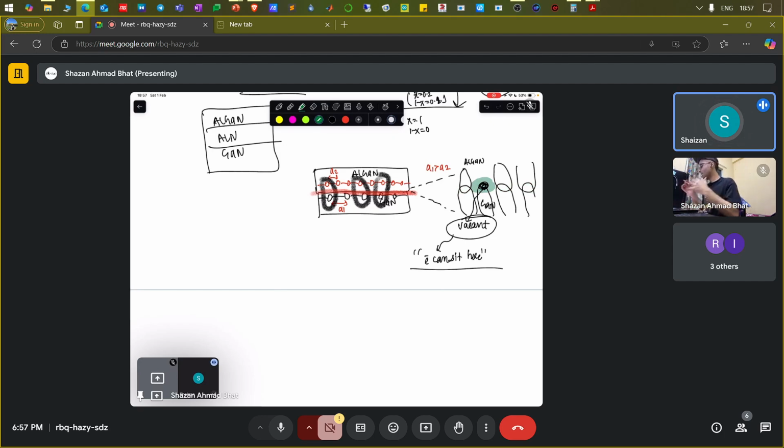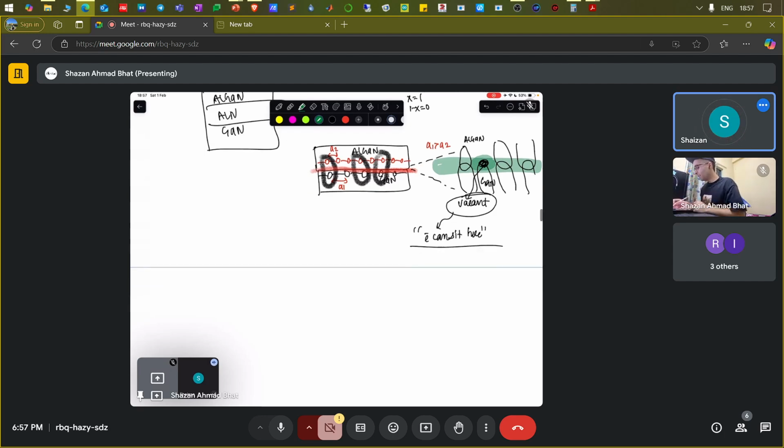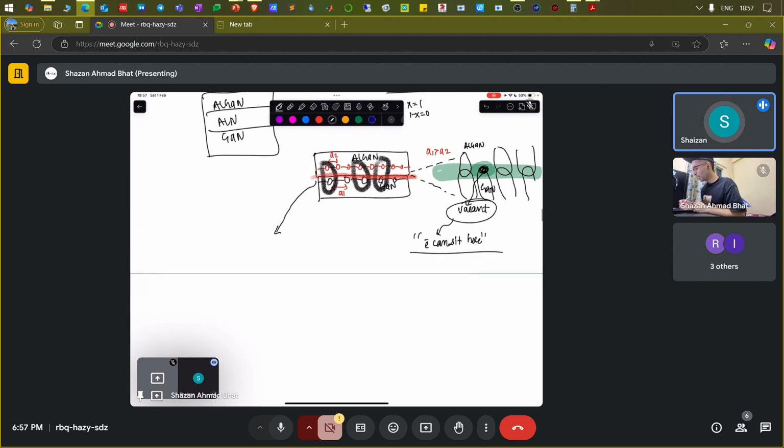So there are thousands, millions of these interfacial states, and you have certain processes in order to terminate them. Something called passivation. You pass hydrogen gas or oxygen gas in order to satisfy some of those bonds, because in the end you have to make a bond with this particular orbital. Once it is done, it can no longer accept an electron, and it will be satisfied. So you can satisfy all of these interfacial states, but it's a very tricky job to make this particular interface. So that is what happens basically at this interface.